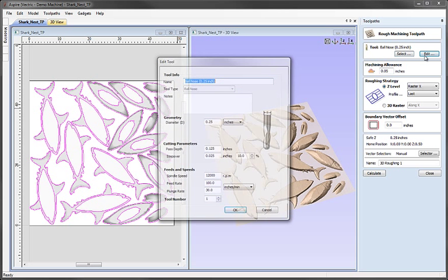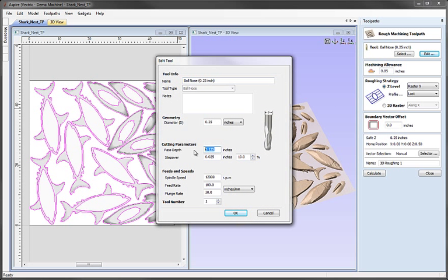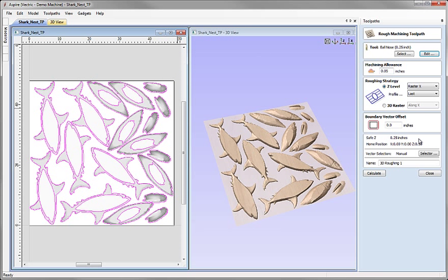toolpath, so I'm going to click on the Edit button and I'm going to enter a pass depth of 0.25, and I'm going to enter a step over in here of 50%. We'll go quite aggressively with this tool in this particular situation as we're roughing soft material. Let's go ahead and hit OK. I'm going to do Z level, raster X, 0 boundary vector offset because we've already offset our vector.